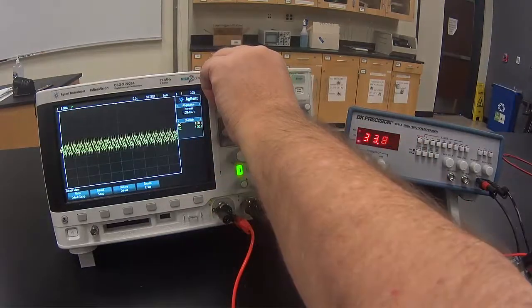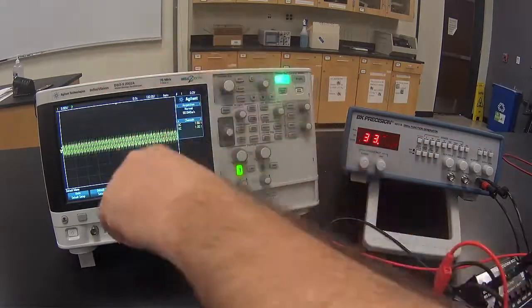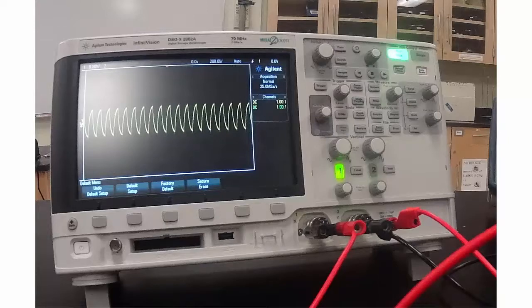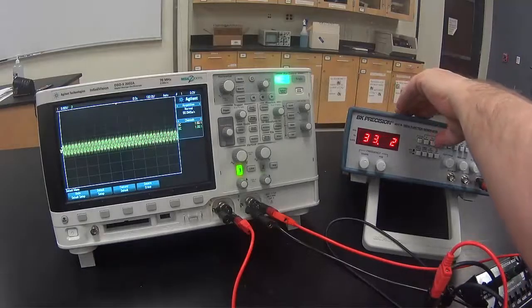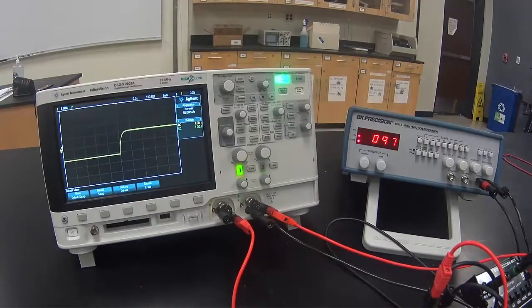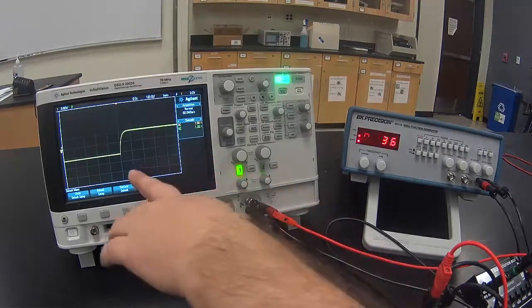You can look at a higher frequency from the square wave and adjust either the voltage or the time settings just to experiment. If the frequency of the square wave is too fast, there's no time for the capacitor to fully charge or discharge. And that's what we see here. Go back to the original 500 range on the frequency.